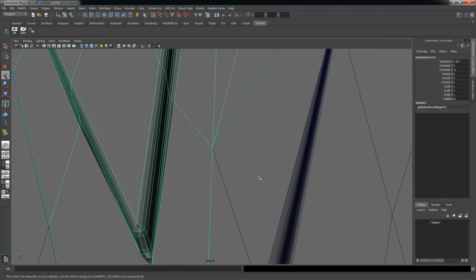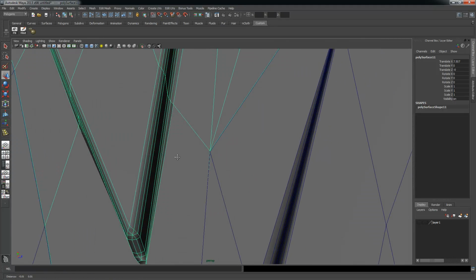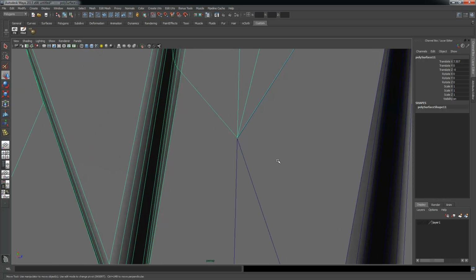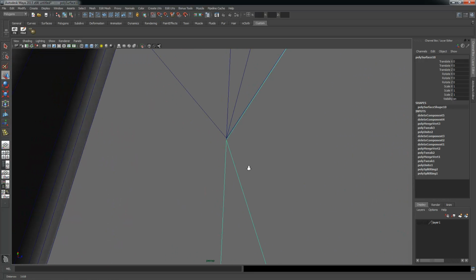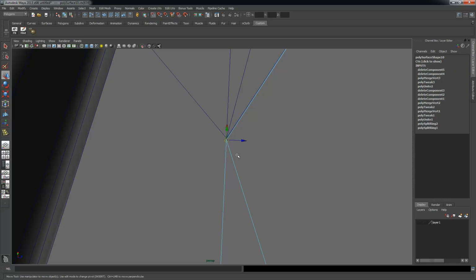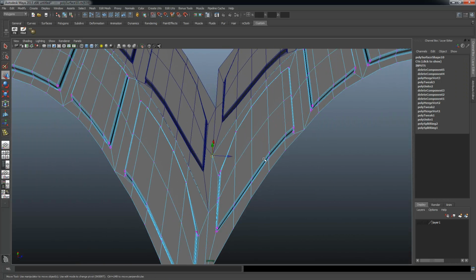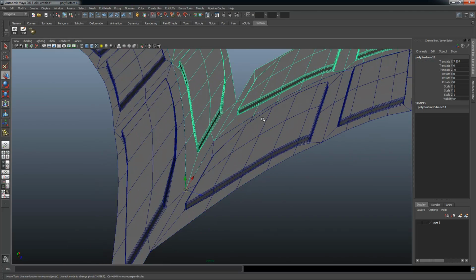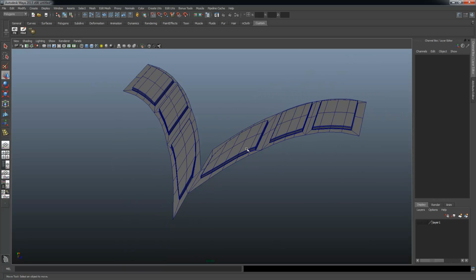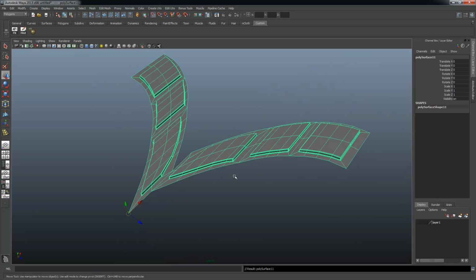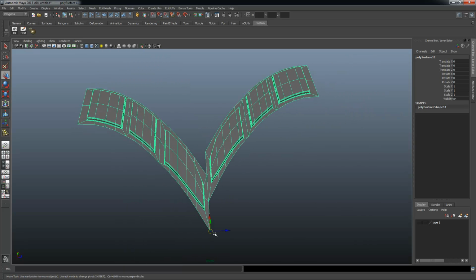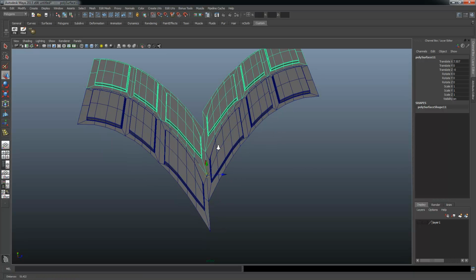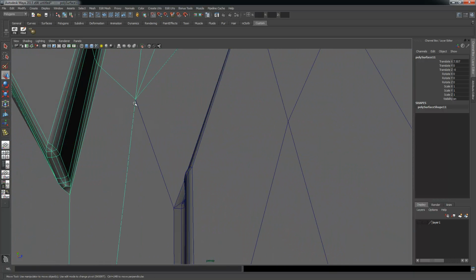And there's an easier way to fix that where the vertices were not lining up completely. That's just for me to go into vertex mode here, grab the offending vertex, and snap it to the vertices of the ones behind. That's going to solve it. Now if I go ahead and delete that, for each successive duplication I'm going to hit Control D and hold down my V key, and there we go. I can check my work. It looks like it's solved.